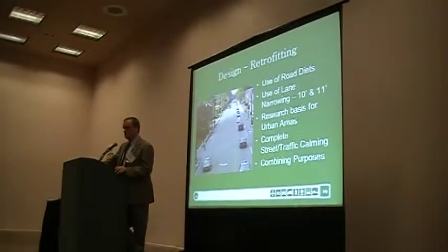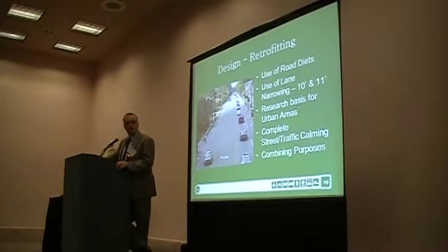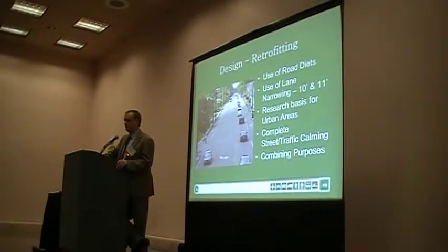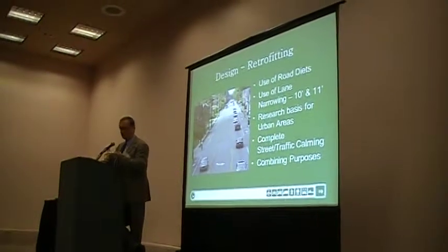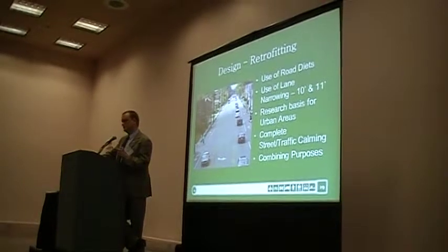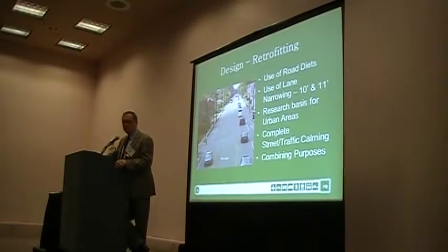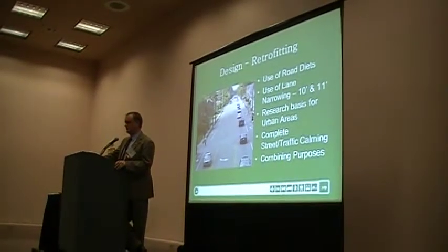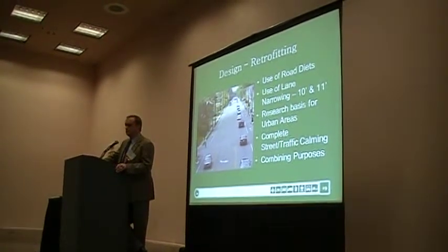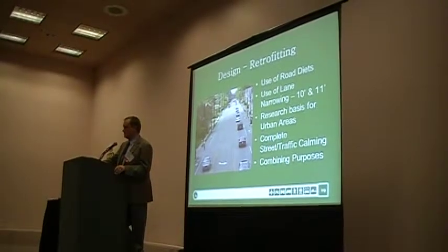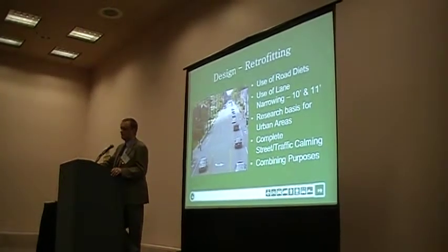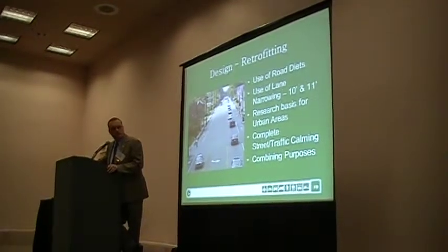We've actually done some applications in some areas, sort of as a combination of traffic calming with providing bike ped facilities near schools, you know, in some areas to provide more buffer, but also to try to slow the traffic down. And we've done a little bit of our own experimentation with putting out radar to check and see the 85th percentile speed. We're finding a few points drop down. I haven't got all the results back. But we're looking at that.